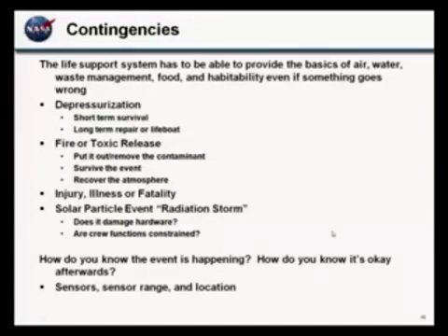Toxic release is a little more dependent on your vehicle. On the space station, we have an external cooling loop that is ammonia. And so we are very concerned about ammonia getting into the vehicle. On Orion, we have a little bit of ammonia to use for post-landing evaporative cooling, so we're still concerned about it. But they've tried to change the fluid. On other vehicles, you may not have any ammonia. You may have something else. You may have propellants that you could walk EVA through if they've been around the area of the engine.